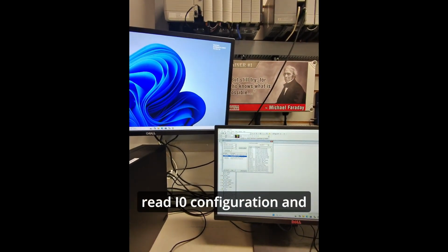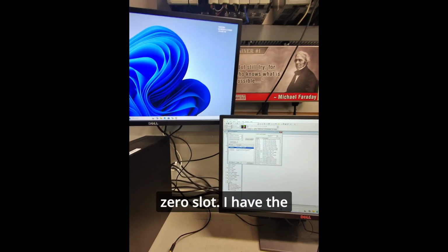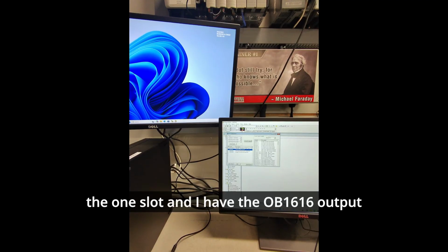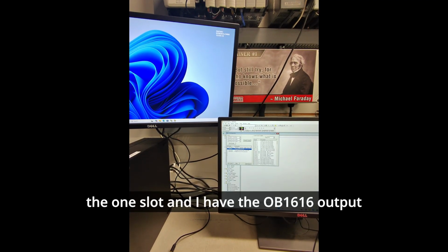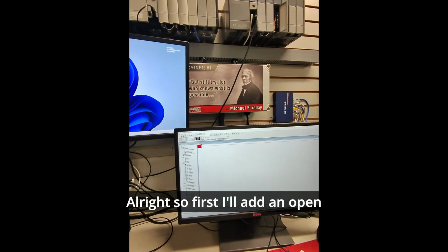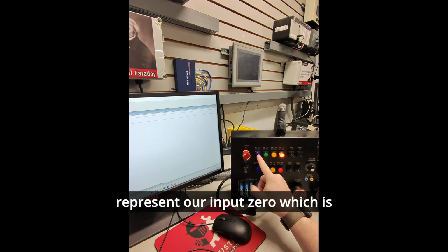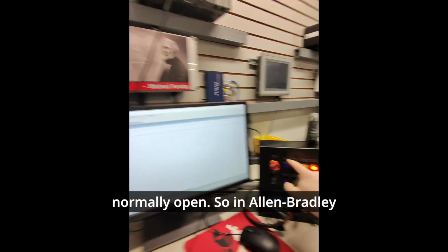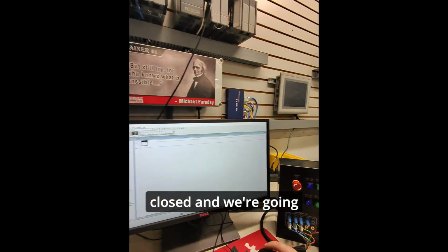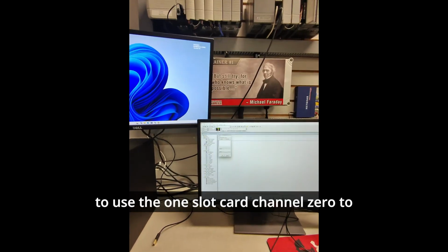So I've done my read IO configuration, and you can see that I have the PLC in the 0 slot. I have the IB16 16 input sync card in the 1 slot, and I have the OB16 16 output card in the 2 slot. All right, so first I'll add an open set of contacts, and that's going to represent our input 0, which is normally open, NO for normally open. So in Allen Bradley, normally open translates to examine if closed. And we're going to use the 1 slot card channel 0 to reference that.